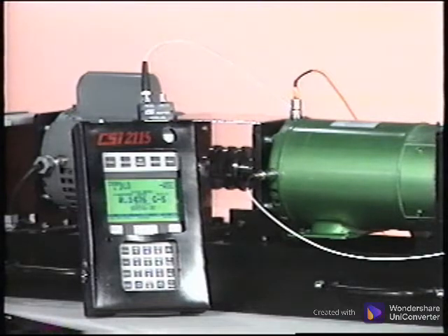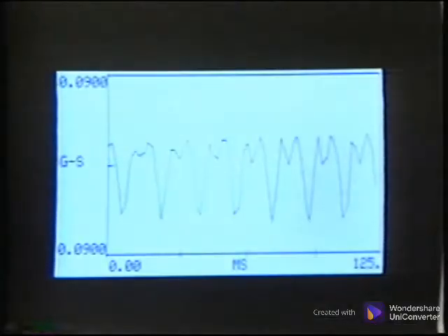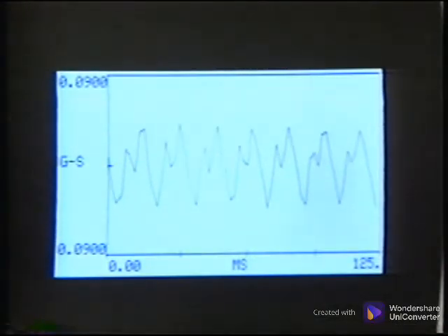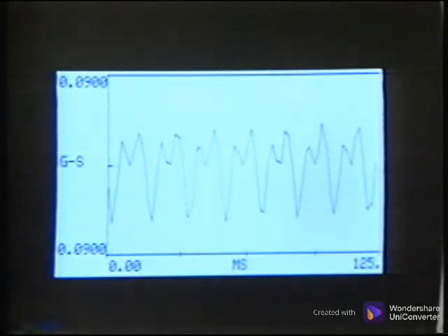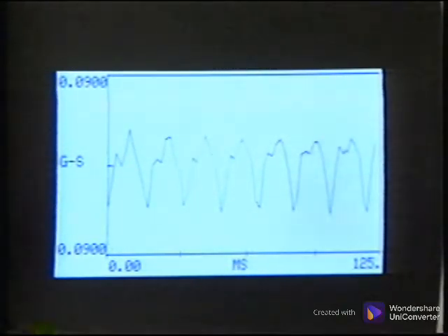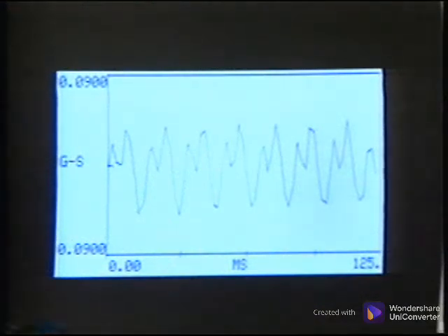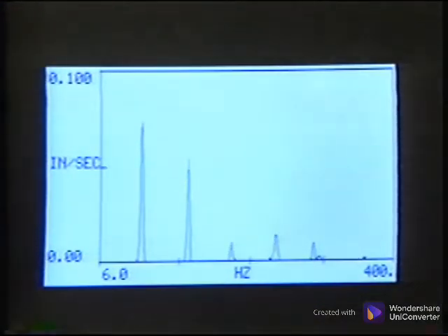Periodic repetitive waveforms can be at the turning speed of the shaft or its multiples. This motor generator set is misaligned, and the waveform is very repetitive, but not all the amplitude is the same. This is because there are actually 2 sine waves, with one of them being stronger than the other. We expect the spectral data to have 2 peaks then, with one being higher in amplitude than the other. Although these 2 examples show synchronous energy creating a periodic waveform, non-synchronous energy can also generate a periodic waveform.